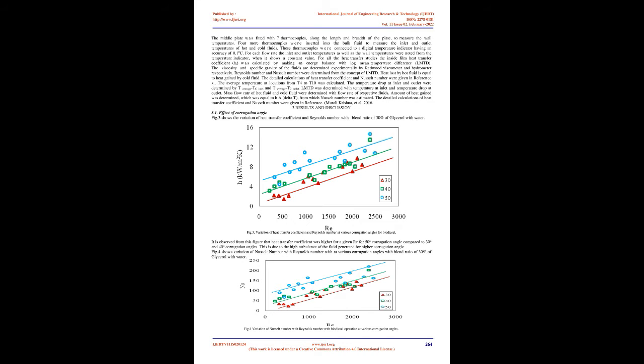Single friction curves, f Reg equals K, for both Newtonian and non-Newtonian fluids were proposed for each by developing an adequate definition of the generalized Reynolds number, Reg. The coefficient K compares well with experimental data, for all tortuosity coefficients. It was found that K decreases with the decrease of n. Fluids, such as food, were frequently processed in PHEs and usually behave as non-Newtonian fluids. This study can be useful in engineering applications as well as in the characterization of transport phenomena in PHEs.